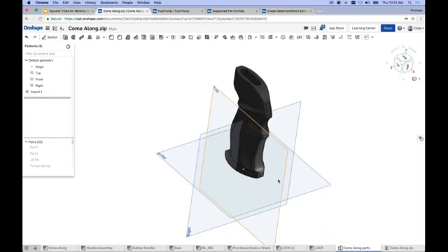So if it was built top down to begin with, and you import it, it would come in that position because that's how it's positioned with respect to its origin. But if you choose to flatten and you bring everything into a part studio, it takes the assembly and then converts that to a bunch of parts that are fixed in the part studio. So important thing to keep in mind.